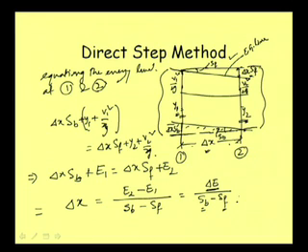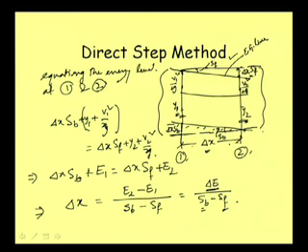Now, one point here is very important: although we are talking about SF, this SF at section 1 and section 2 will not be the same value. We can compute this SF using Manning's roughness formula or Chezy's roughness formula, but whichever way we calculate, we will get two different values of SF for section 1 and section 2. So what SF will we use for computing the delta x?